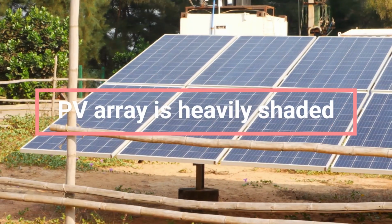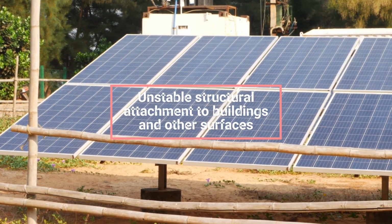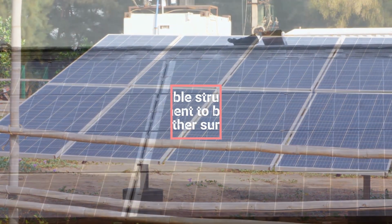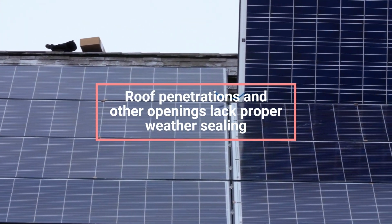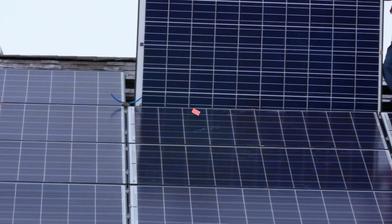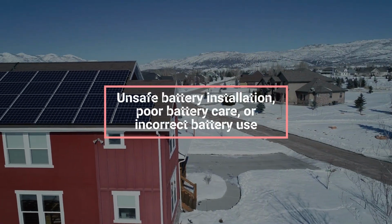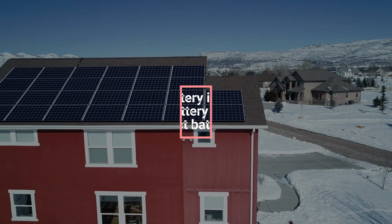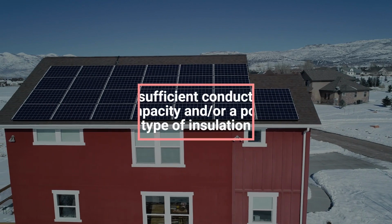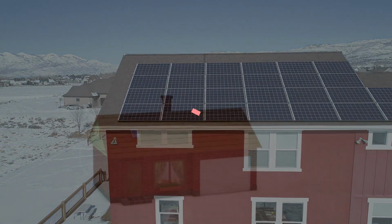PV array is heavily shaded. Unstable structural attachment to buildings and other surfaces. Roof penetrations and other openings lack proper weather sealing. Dangerous wiring. Unsafe battery installation, poor battery care, or incorrect battery use. Insufficient conductor ampacity and/or a poor type of insulation.